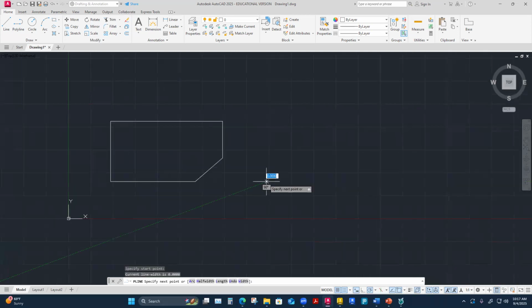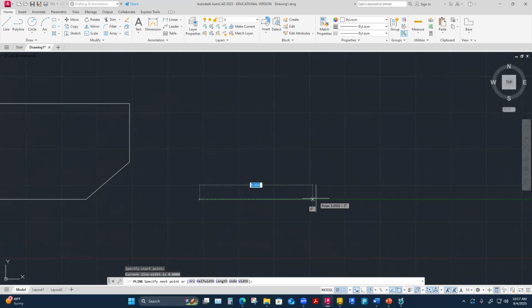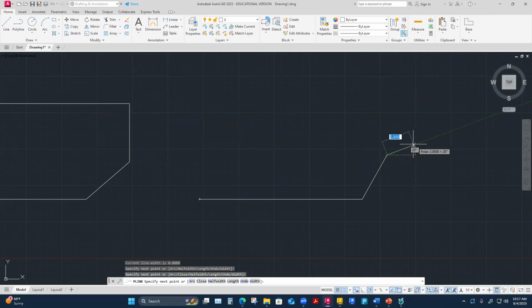And that's just going to help me keep some alignment. I use that for orthographic projection alignment sometimes. So right now the bottoms are aligned. I'm going to draw roughly the same shape. It's not to any dimensions whatsoever. But if I want to line up the top, maybe I'll hover over here for a second and then come back, and that line should show up. That shows me that I'm going to be perfectly in line and at the same dimension there.